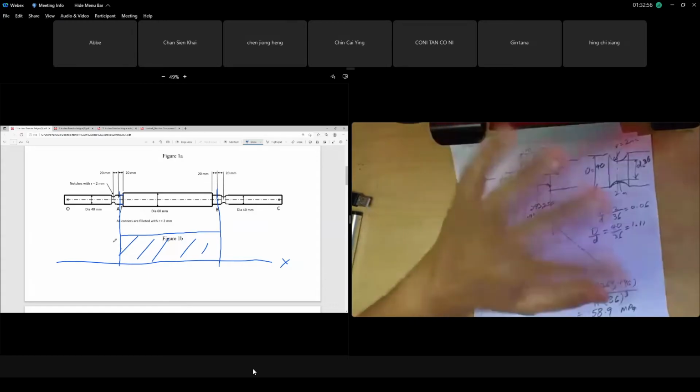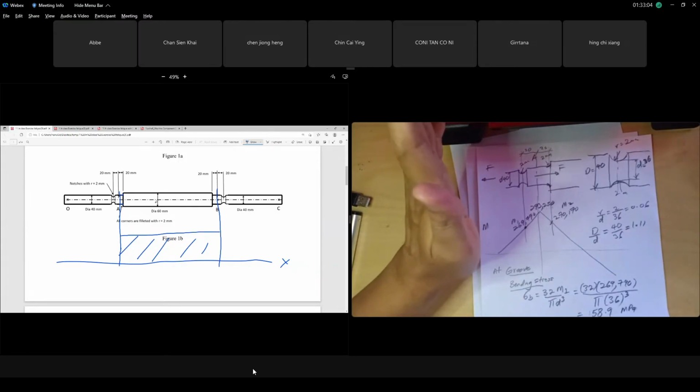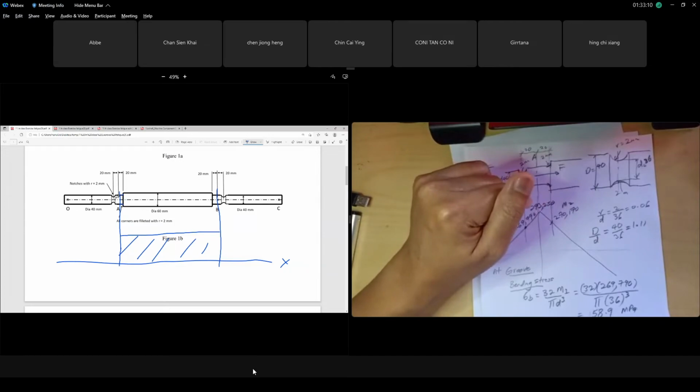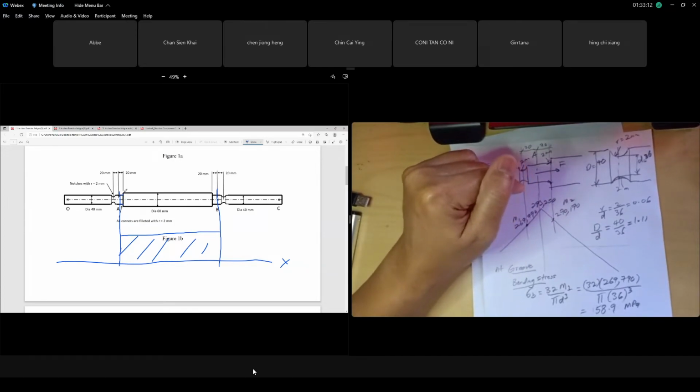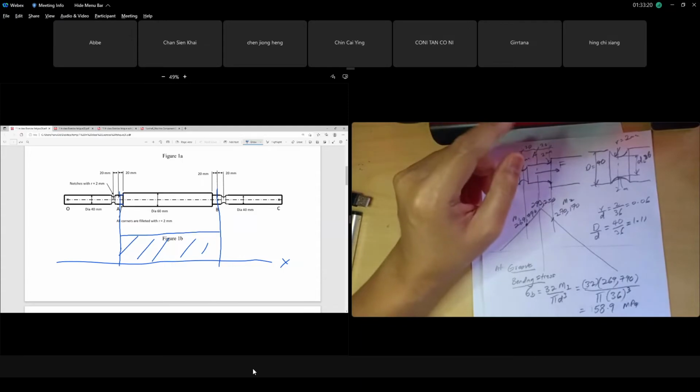No, yes, you are right. No torsion, because torsion only starts at A until B where it cancels out. Torsion only happens from A to B. Before A, no torsion, and the groove is before A. But the shoulder has torsion. Okay, now since at A there is no torsion, be careful. At A, there is no torsion.